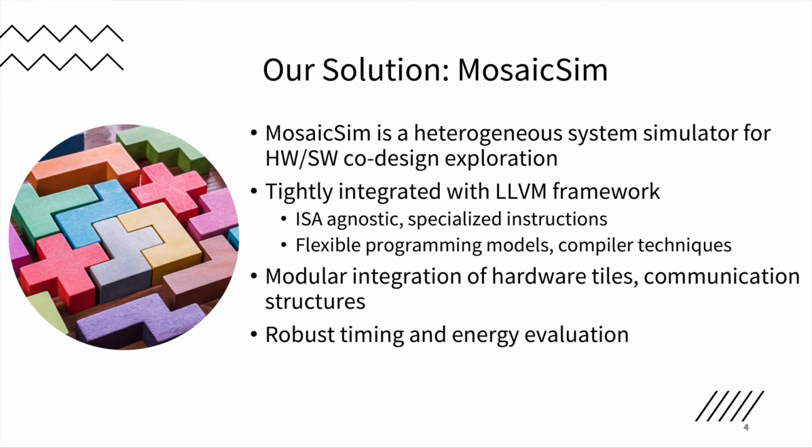To solve these problems, we introduced MosaicSim. MosaicSim is a heterogeneous system simulator that's designed for hardware-software co-design exploration. MosaicSim is tightly integrated with the LLVM framework, which makes it ISA agnostic and allows it to support specialized instructions. It also allows for flexible programming models and compiler techniques.